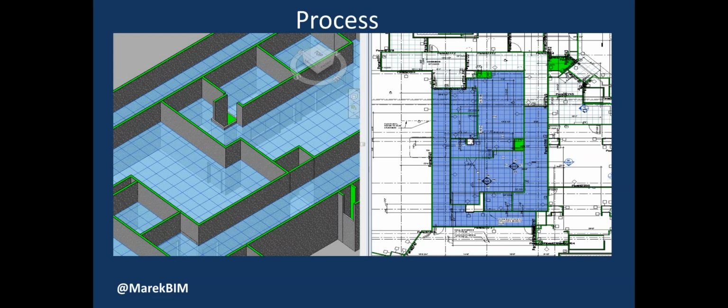So we'll take an architectural model and we'll check it first for the tolerances, and we'll set our tolerances. Usually it's a minimum of 1/16. We'll set it, and this avoids any rounding issues that would throw our dimensions out. And then we'll modify the property of the wall to allow us to change colors as we make changes so we can keep track of the work we've done.